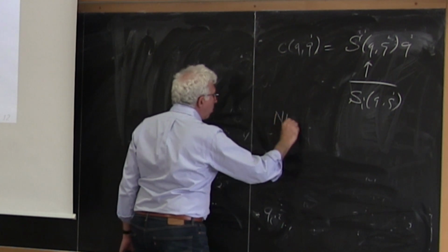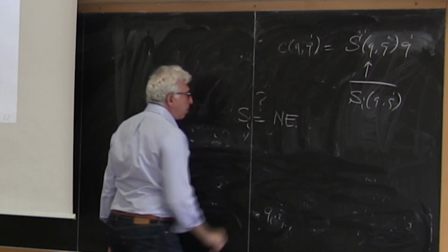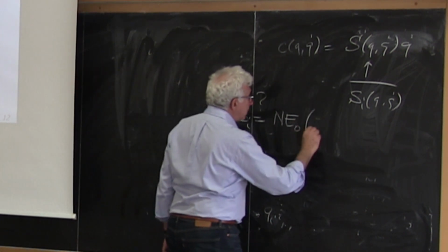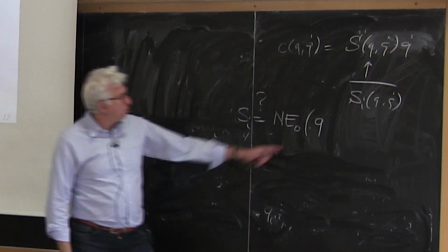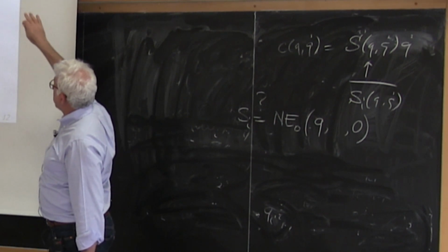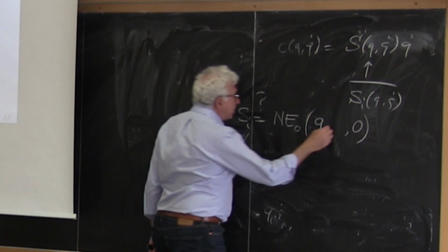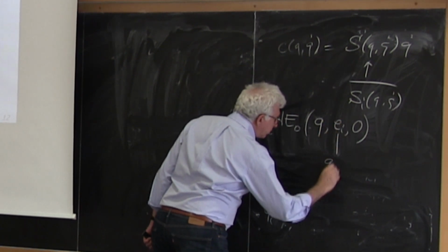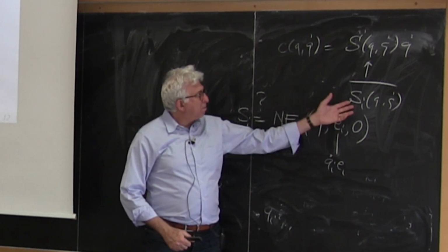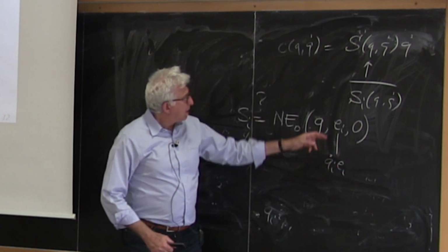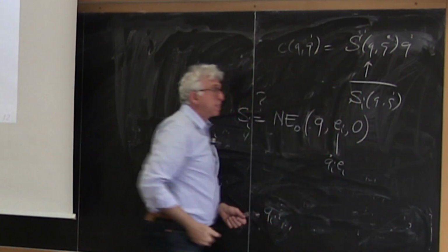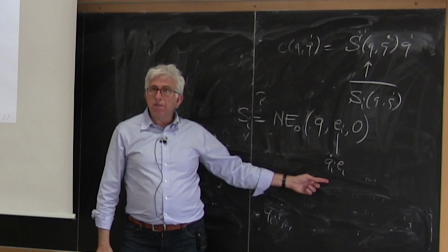Now, if you call, I put a question mark here, if you call this with 0 subscript so that you eliminate gravity, and you certainly have to call this at the configuration Q, because Q is here inside, you would like to eliminate acceleration, so the inertial term is gone, the gravity term is gone. I'm focusing now on this. And if you put here e_i, or even q_i dot e_i, then you may take a column of this, but in fact, you're using the wrong velocity inside this matrix. You will find the matrix evaluated at this specific velocity vector, which has only one scalar component there.